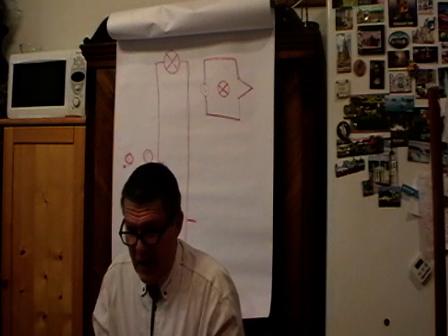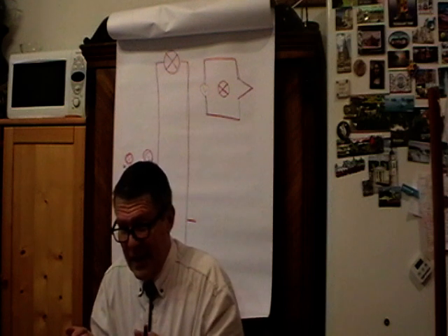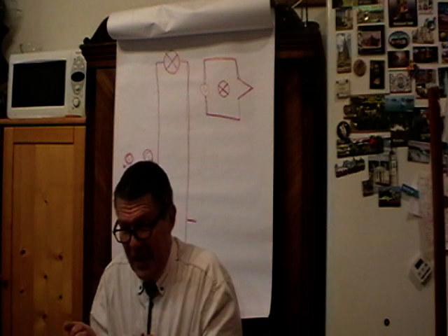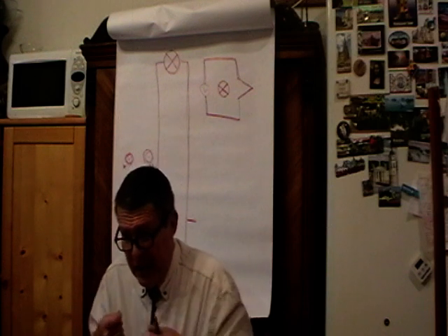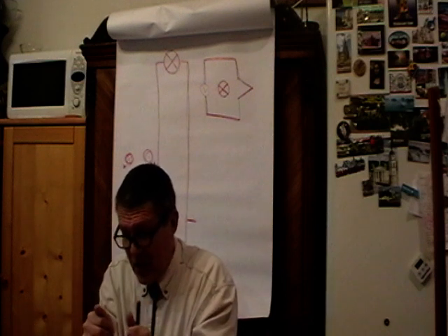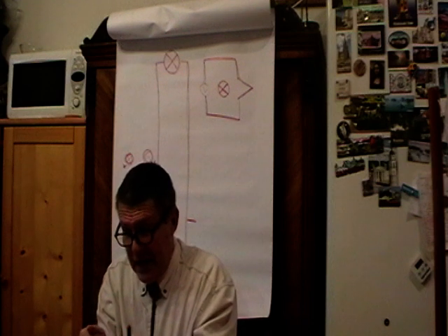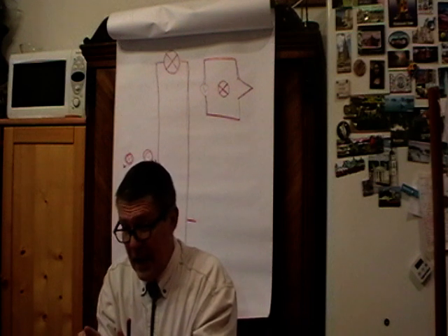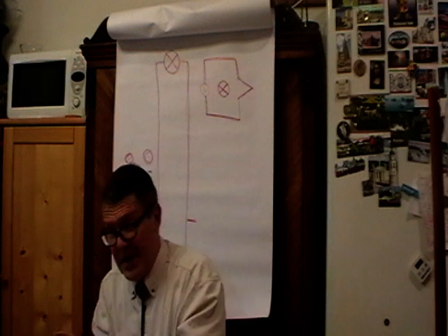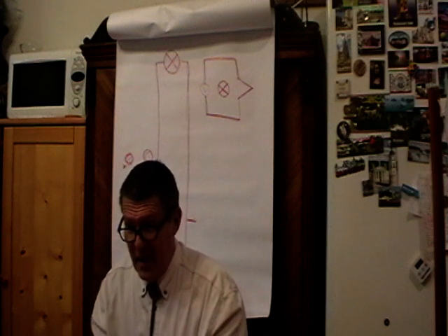Which voltage and current? Well, if you supply a voltage to that line, you need to charge the line, and that current would be the current bringing in the charge. So if you just connect the source, the line would charge, and to do that it will need for a short time some small current. The ratio between the voltage and this current is called characteristic impedance of the line.